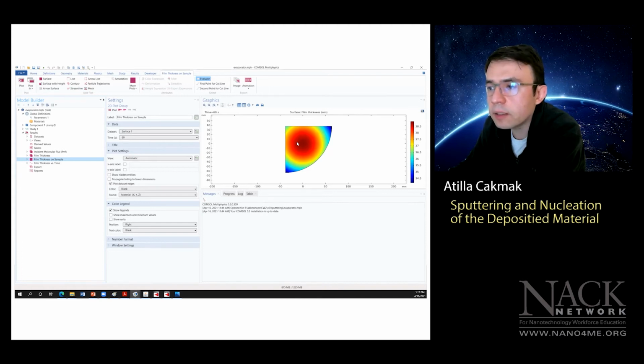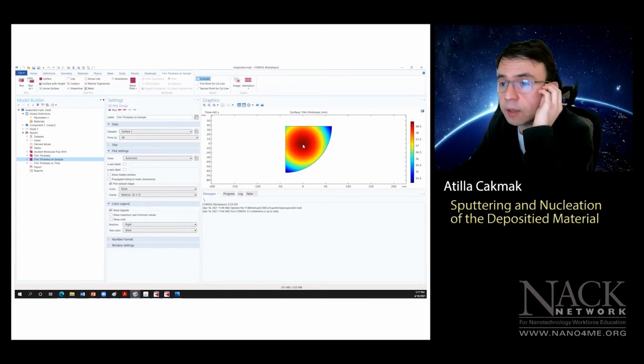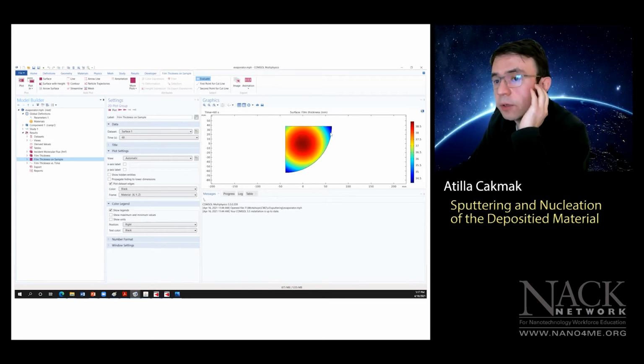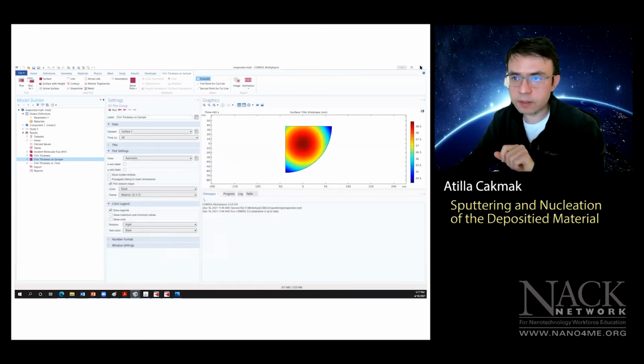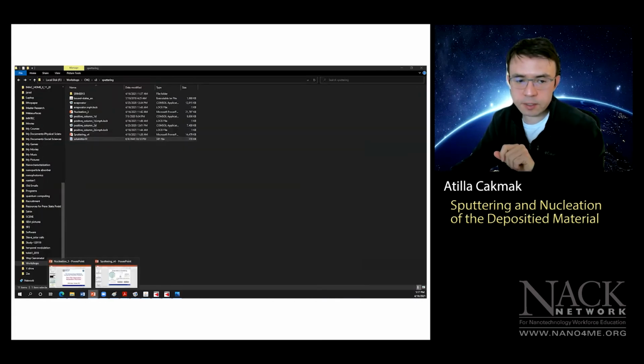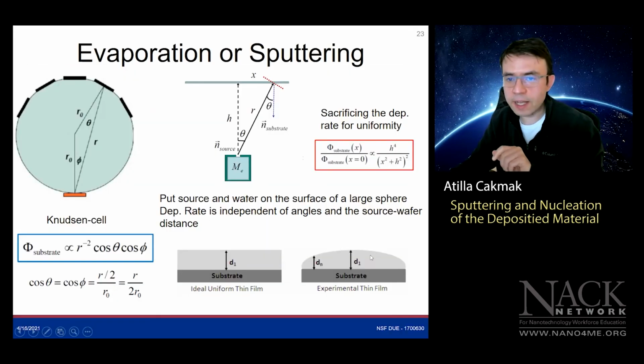Yes, it is COMSOL again, Abdulali. So at the end of the 60 seconds, we have the most thickness in the middle of the wafer. I was just simulating a quarter wafer, like you can see on a regular silicon wafer. There's the most aluminum deposited in the middle, and at the edges it goes down to 35. It's because of the selectivity of the deposition with evaporation. When we have evaporation, it's what we call a line of sight effect. It sees the direct line immediately. It sees the edge at a tilted angle, so that drops down the deposition. You can think of it that way.